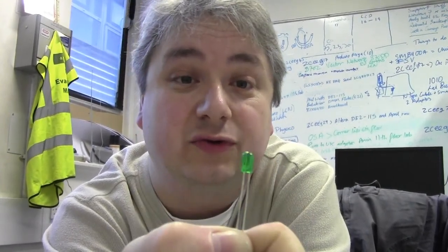The only other difference really between this and a standard diode is numbers again, and that's in reverse bias characteristics. The reverse breakdown, a point of no return: you take it over that value in reverse and you will destroy your diode. LEDs compared to diodes are extremely small. Standard diodes may be 40-50 volts and up in reverse before you actually destroy them.